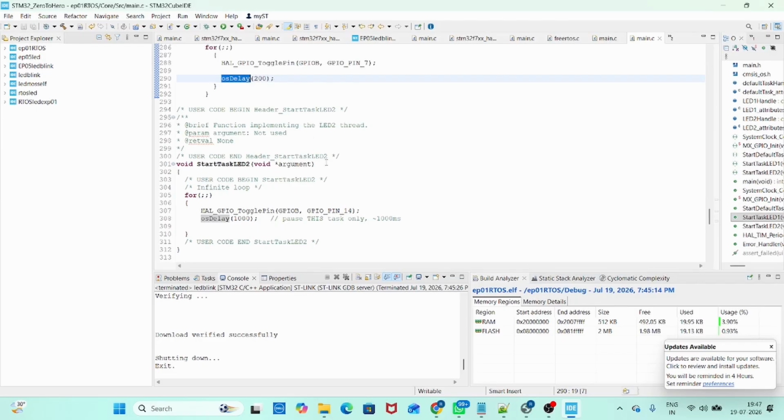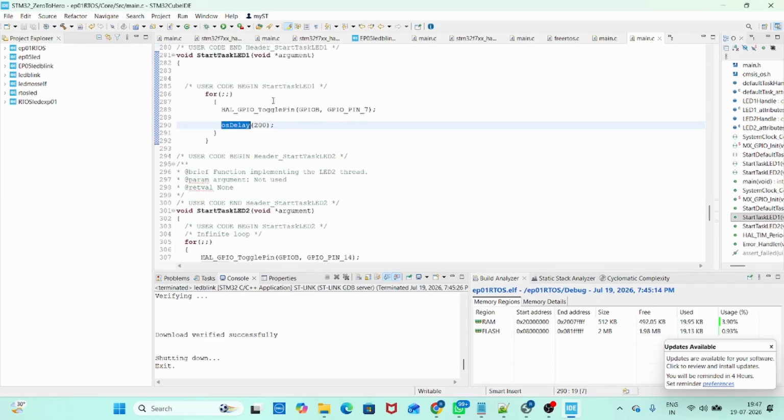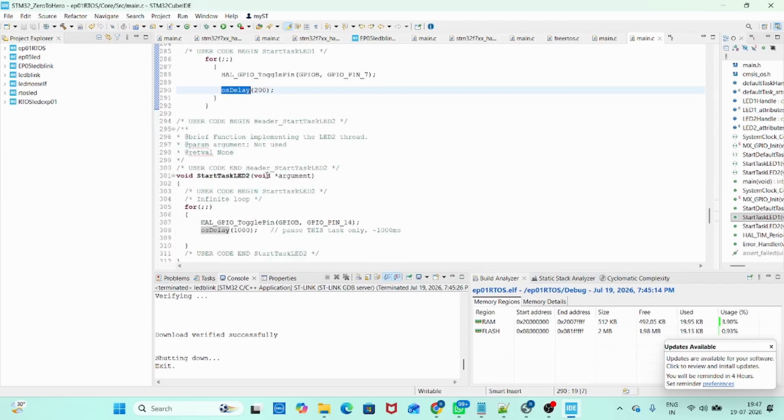And here you can see that task 1 or task 2, none of the tasks is blocking any other task, right? Because after the operation they simply go to sleep mode. So this is specific to this function only. Same way with this. After executing this for 1 second, this task will go into sleep mode, or you can say it will release the resources, so another task can be executed. So it's basically the multitasking concept, right?